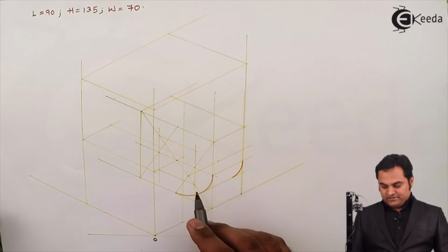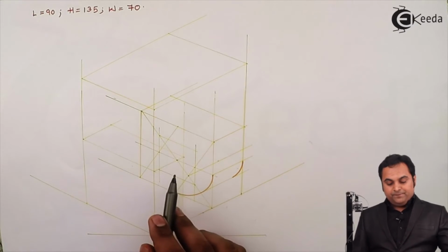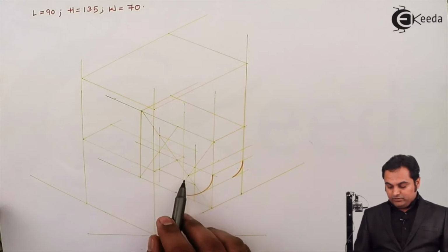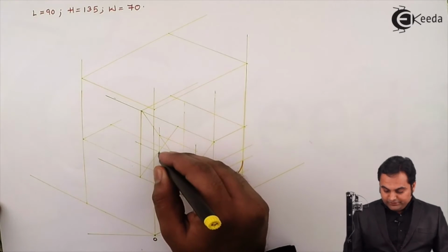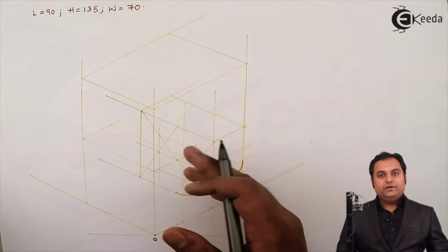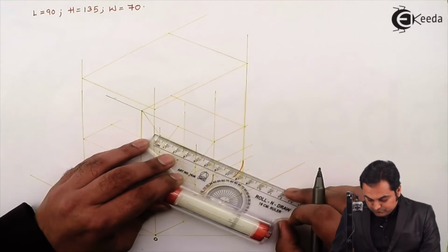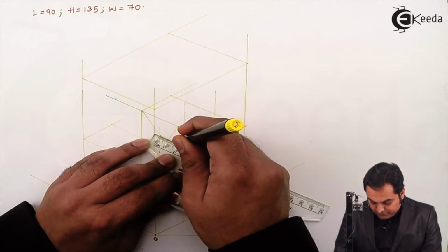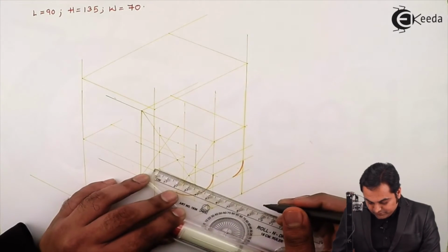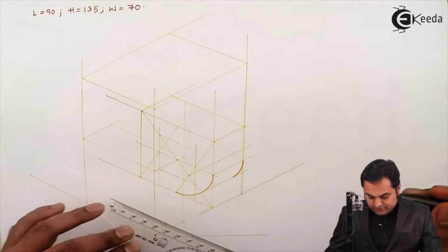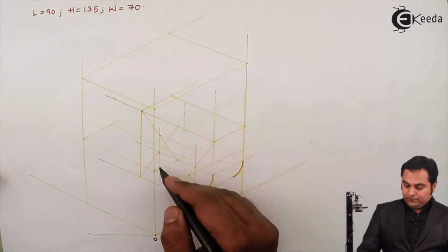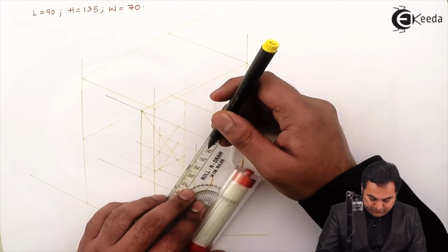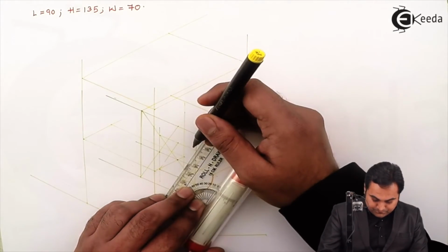And again the method is the same. First the longer diagonal, and here the longer diagonal of the outer parallelogram and the inner parallelogram is the same. Next, already two midpoints are there. I need to get the other two midpoints. For that, this is 35 mm, so taking 17.5 and 17.5 to get the midpoint. Now the top midpoint again will be joined to its opposite corner, bottom midpoint to its opposite corner.